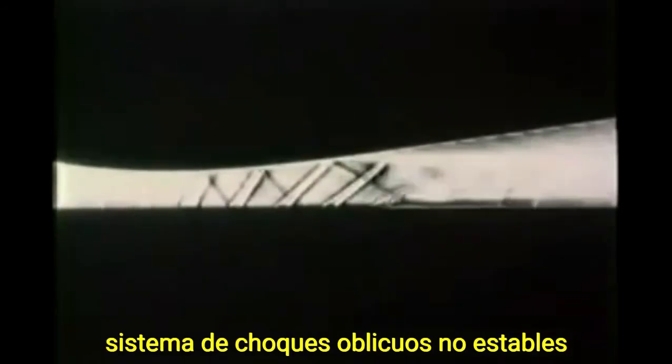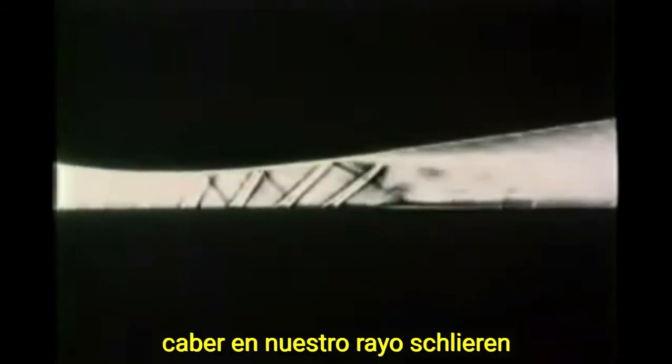In fact, the shock wave in this channel turns out to be not a single normal shock, but a complicated system of non-steady oblique shocks. The boundary layers are separating from the walls of the channel. This is because certain viscous effects are exaggerated when we make our channel small enough to fit into our Schlieren beam. The sound you hear is being picked up by a microphone at the channel entrance. Noise from the valve and piping can only propagate upstream to the entrance if the entire flow is subsonic.